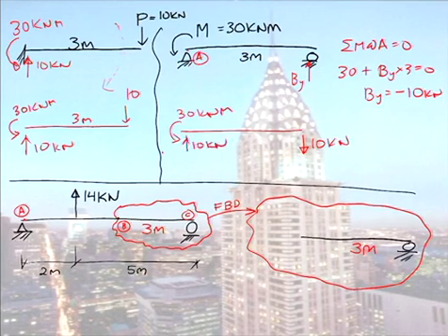So once again, can you see these two systems are identical? So whether it's a beam or a truss, or the systems could look different, a cantilever or a simply supported beam, they're the same. In this third diagram down here, I have a simply supported beam with a point load up of 14 kilonewtons. Taking moments at A here, can you imagine my C reaction here, is it upwards or downwards?